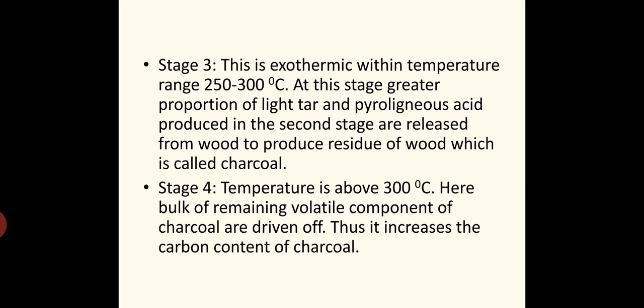In the third stage, heat is further provided at higher temperatures. But the difference from the second stage is that here it is an exothermic stage, within a temperature range of 250 to 300 degrees Celsius. Exothermic means during the chemical reaction, heat is also liberated. At this stage, a greater proportion of the light tar and pyroligneous acid produced in the second stage are released from the wood, leaving a residue of wood, which is called charcoal.